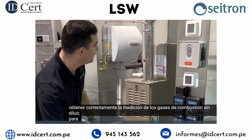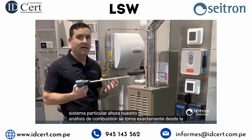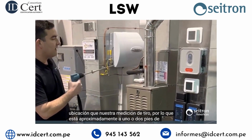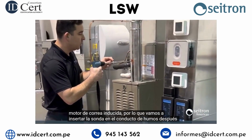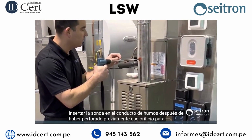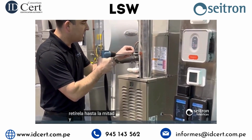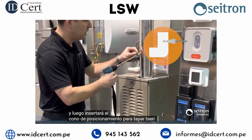All right, so for this particular system, our combustion analysis is taken from the same exact location as our draft measurement. So it's about 1 to 2 feet away from the induced draft motor. So we're going to insert the probe into the flue after having previously drilled that hole, touch the back wall, and then draw it back about halfway. And then you're going to insert the positioning cone like so to plug up that testing port.